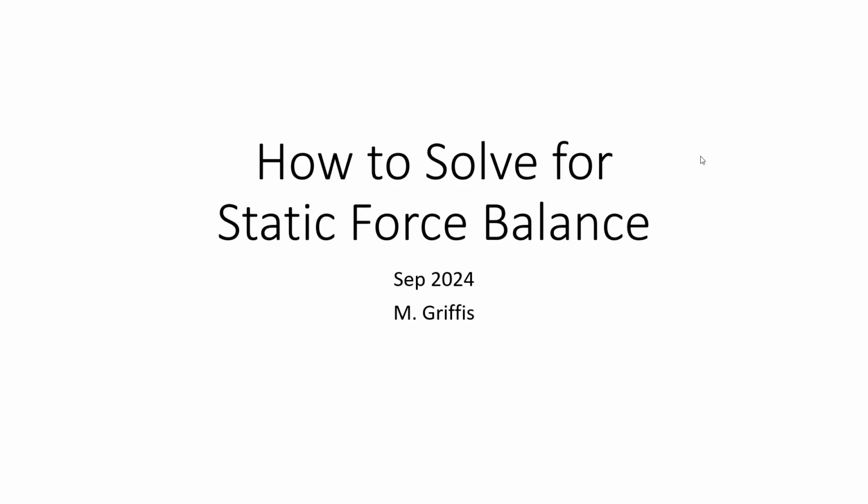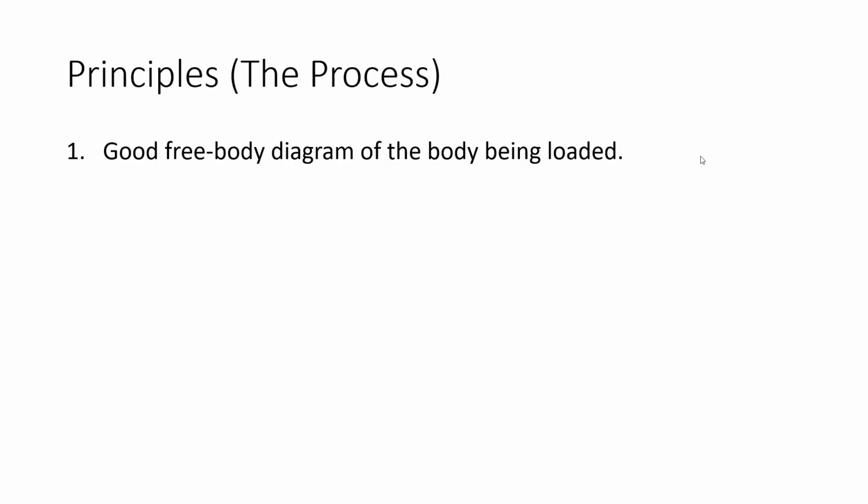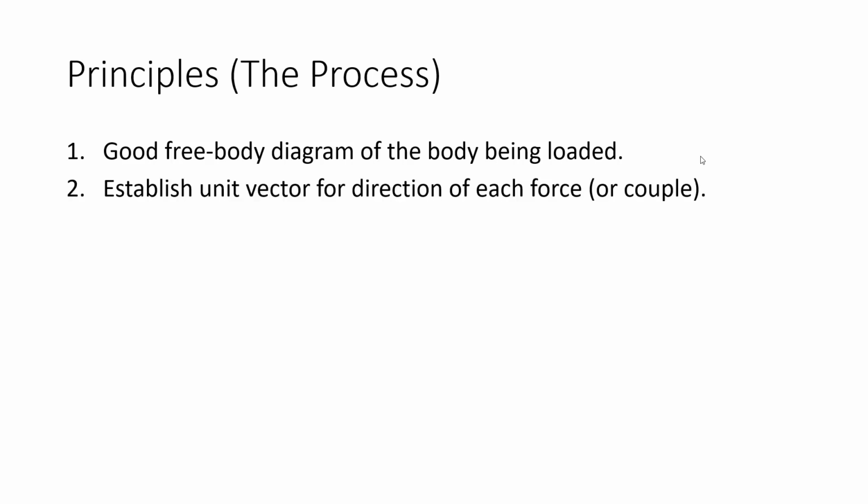Hello, today I want to talk about a method for solving static force balance problems. The method relies on 7 steps. The first step is get a good free body diagram.